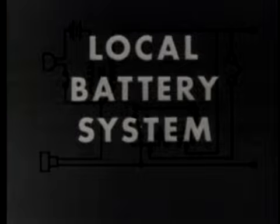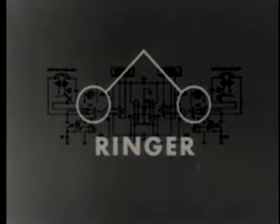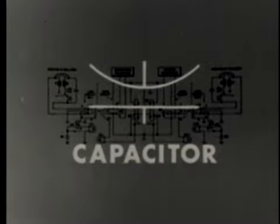You will see how the sound-powered system, the local battery system, and the common battery system utilize generators, ringers, transmitters, receivers, induction coils, and capacitors to carry the sound of our voice over 2 simple wires. Actually, our line forms a closed circuit through terminating points, connecting 2 stations on a point-to-point line.